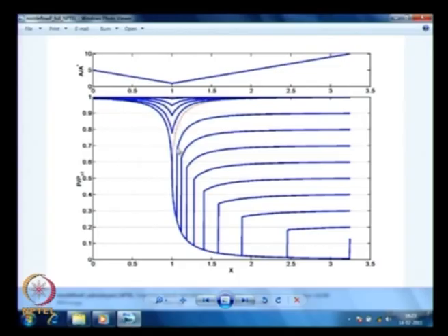So if you see what is happening, I have plotted for a linear nozzle, straight line nozzle. This curve does not change beyond that point, the subsonic part does not change. Why? Obviously this point gets choked, and whatever happens downstream, nothing gets affected upstream of that Mach 1 condition. This is the choked condition, nothing upstream changes beyond that point. So this curve is the same for all these curves, starting from this red dotted line all the way till all these curves to the left of x equal to 1 is all the same. Every curve is one on top of the other.